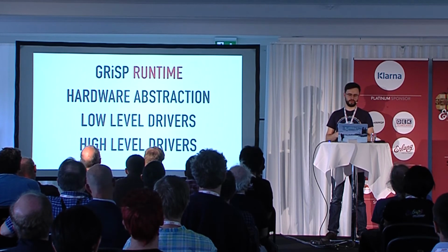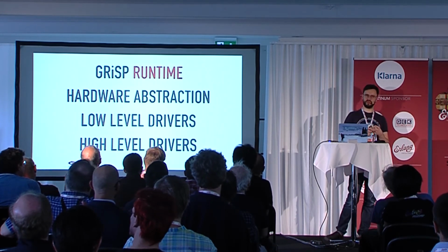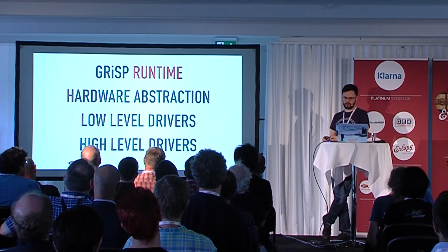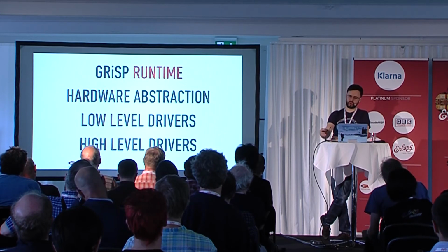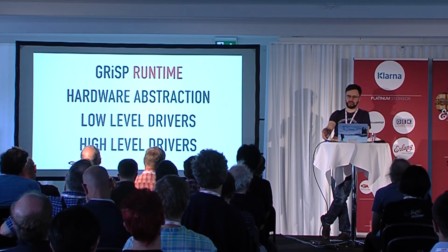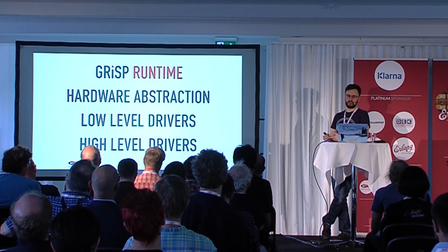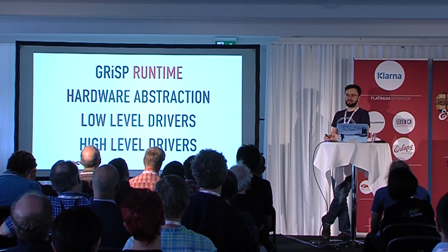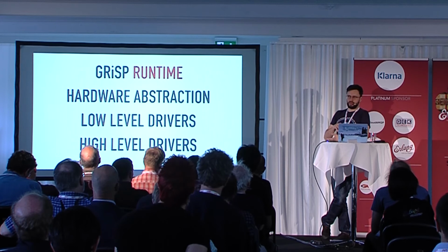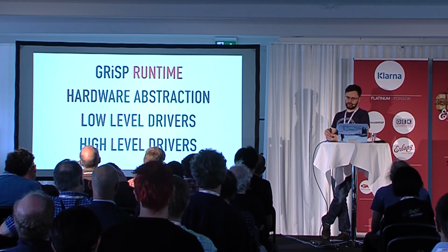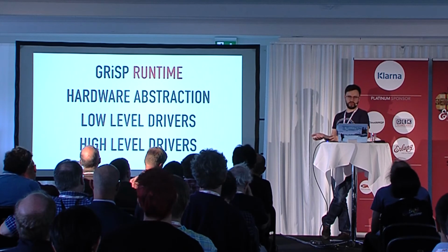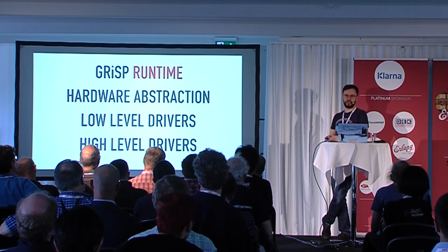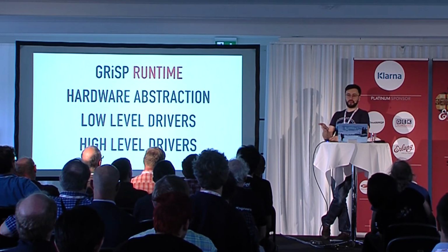So the GRiSP runtime, it's just an Erlang application. It's a couple of linked-in drivers as well to talk with the hardware. So for example, when we need to talk GPIO, so one of the GPIO ports, or for example, check the switches or modify the LEDs, we use a driver for this. And we have a driver to talk to SPI. So we have a C-level layer provided by RTEMS and by the implementers of the hardware board, which interfaces with the SPI protocol. And we then have bindings for this to Erlang, so you can send and receive SPI commands. And this is, for example, how the accelerometer driver is implemented.